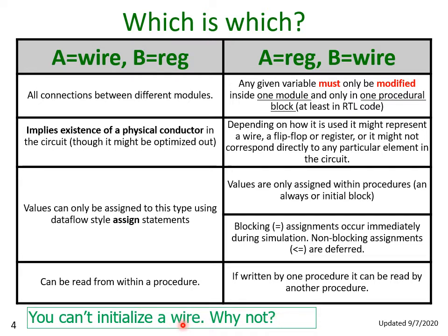But in a circuit, if that variable or that wire type corresponds to a wire, all it can do is connect things to each other. Even if you assign an initial value during simulation, that initial value will be ignored basically during synthesis. All that matters in the circuit is what circuitry is putting a value on that wire. So the wire itself you can't initialize.